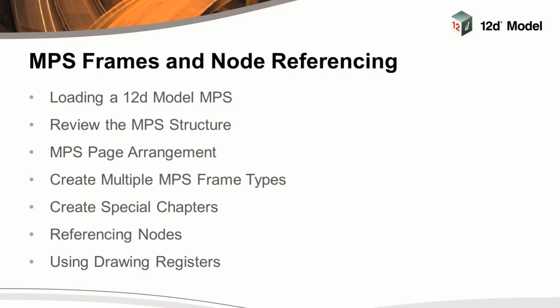So today's content, we're going to be doing, as I said, MPS Frames and Node Referencing, and that's going to include the following items: loading a 12D model MPS, review the MPS structure, MPS page arrangement, creating multiple MPS frame types, create special chapters, referencing nodes, and using drawing registers.